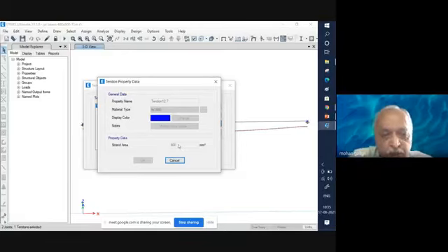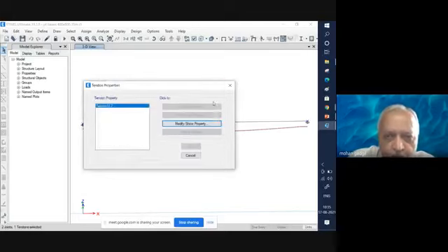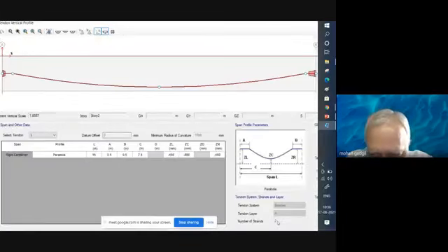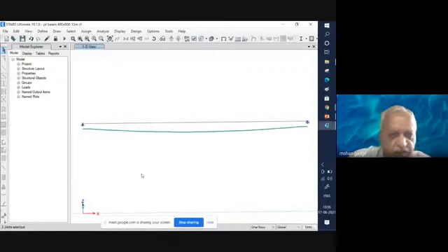So in all, I have provided 12 strands, but the definition is given in this way, that individual cable I have taken as 600, but there is no cable of area 600. It is 6 strands, which I am calling one single cable of area 600 mm square, and I am providing 2 such cables over here. If you see this particular cable that I have considered, you can see at the right hand end over here, can you see this arrow? The number of strands I have taken is 2. Now individual strand I have taken as of area 600, which is equivalent to 6 cables of 12.7 diameter. Okay. Now this is the way I have considered the data.